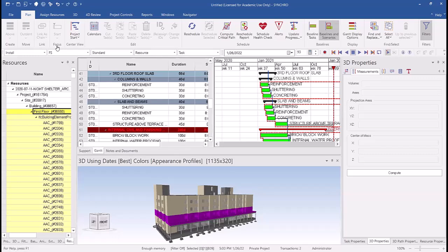So now we had one question here in the chat box. Usually the BIM models are complex and have lots of elements. How much processing or cleaning up of the BIM model is required before it can be used in Synchro? It's not required much, because you can filter it out here also. We can remove the activities from here as well, and remove the resources from here. Whatever we don't require in our model, but as of now, if you're connecting with your schedule, you will be needing the complete BIM model. The things which are not required, you can unload from here as well.